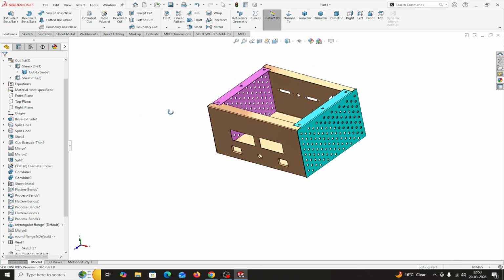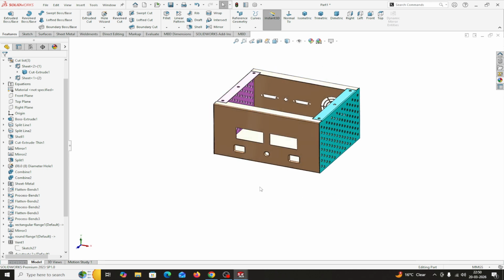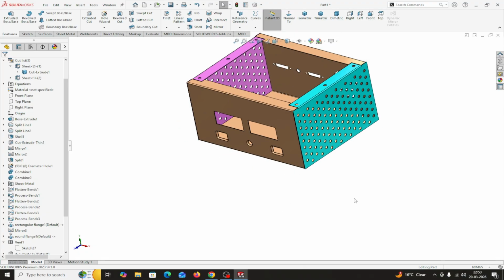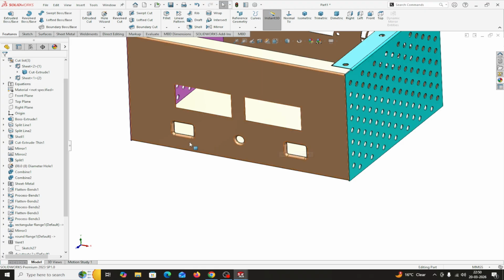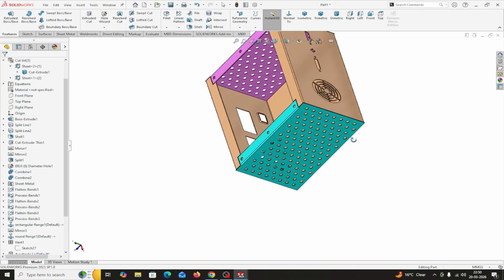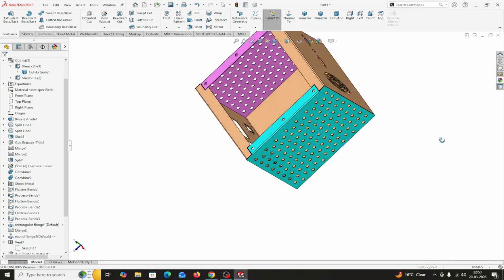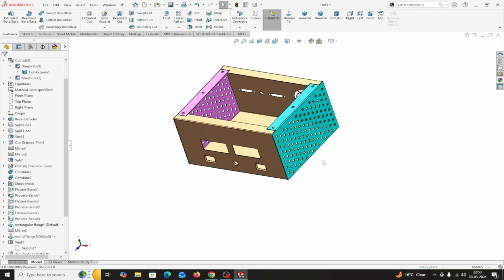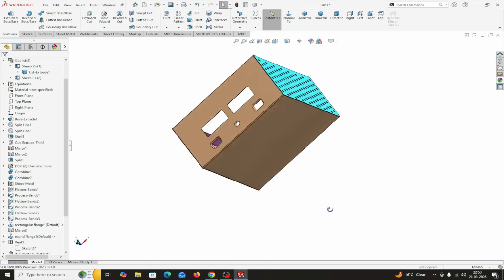So first in this exercise I made the solid body 3D model, and then I split these 3 parts, and later on I converted them into sheet metal and applied the shell feature. With the help of the forming tool, I placed the extrude and round flanges, and this vent feature I have made. This is used for ventilation purposes. This is also for ventilation; this is used for the electrical items.